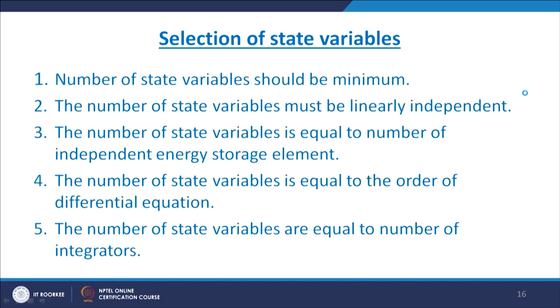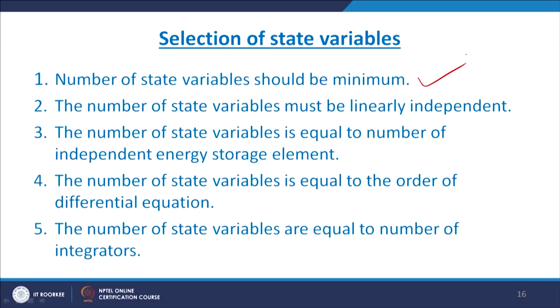Now, the selection of state is very much important in state space analysis. Which state should we take? The general logic given here is that we have to select the state which has energy storage elements. Whenever a problem comes to you, you have to see how many energy storage elements are there. Number of energy storage elements equals number of states. So the first point is that the number of state variables should be minimum.